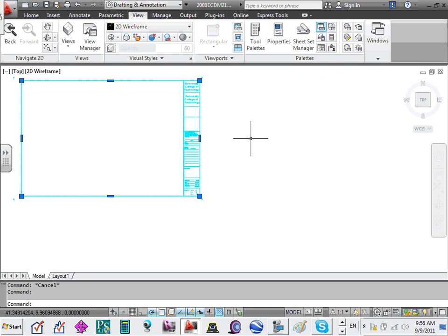The key note about this one, this title block matches a 22 by 34 page. So when you measure it, it has to be within 22 by 34. Really, this is the key pointer. Other than that, it's just lines and text. So if I'm going to design a title block for 8.5 by 11, this is not my title block. Sometimes you can scale it when you print it by fit to page and so forth. But if you want to design one for 8.5 by 11, this is not your title block. Or 11 by 17, not your title block. Though when we print, it allows you to scale down. We print to 11 by 17. That's a different story though.